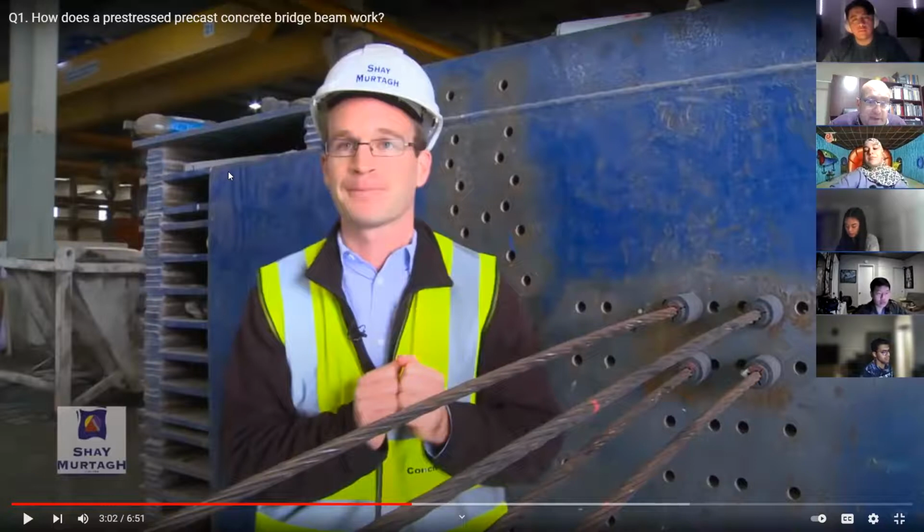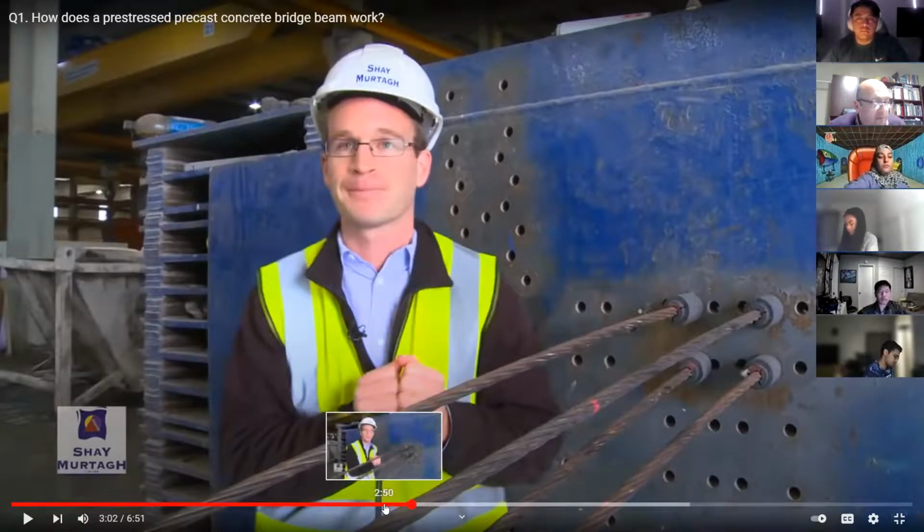Pre-tension, because concrete poured after. Because this is going to be in the fabricator's yard, right? This is in the factory, right? Okay. Would you have bond from day one between the concrete and the strands? I'm going to say yes, absolutely. Okay. Do you expect that this beam is going to be exposed to positive moment or negative moment?